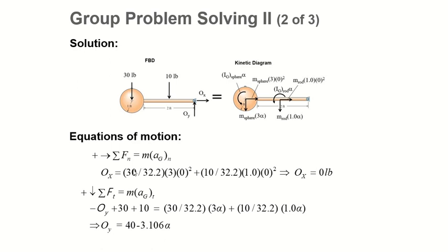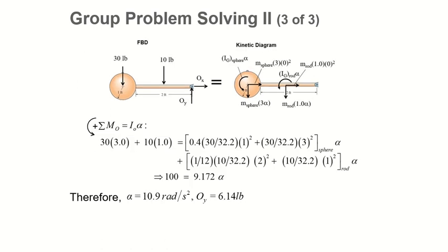for each of your axis n and t, we get the sum of the force. Once you get that, we're going to put it back into our same equation again, plug it in, and you will get the angular acceleration. Use that angular acceleration to find the reaction at that point. Oy is this, and then Ox, meaning what the total resultant force is going to be at that point. So here we're giving it in terms of weight.